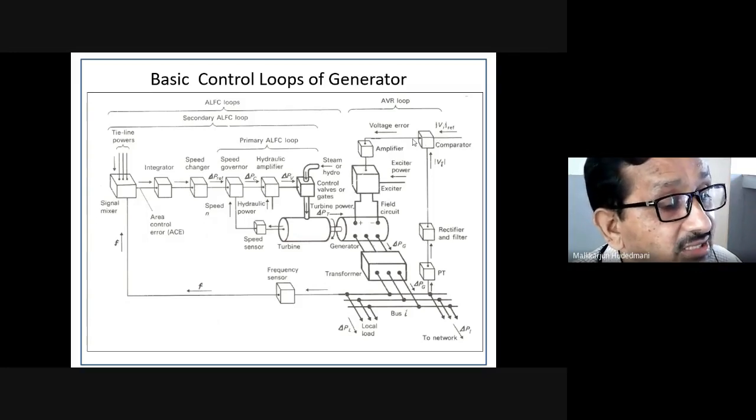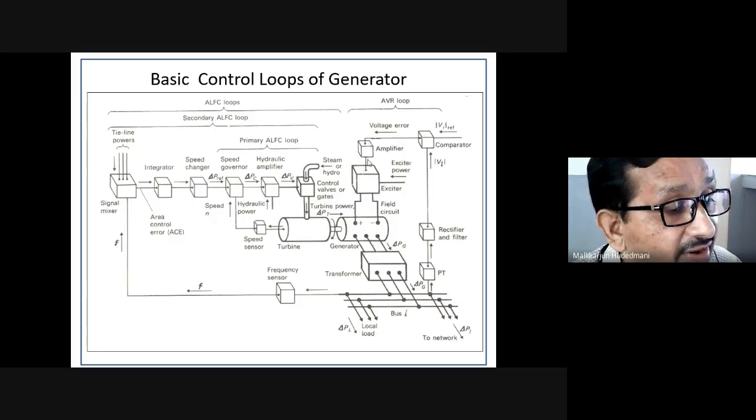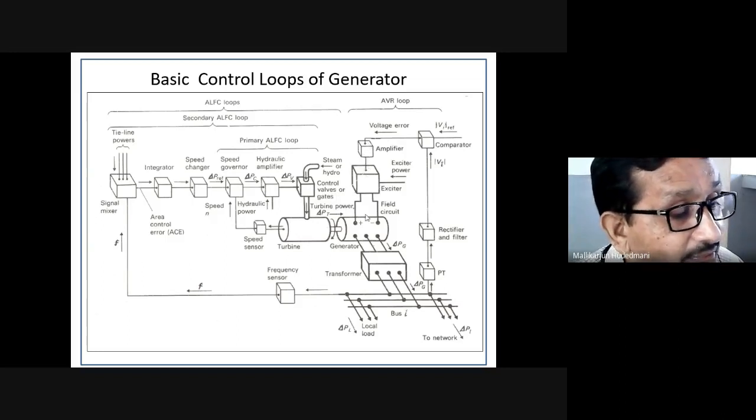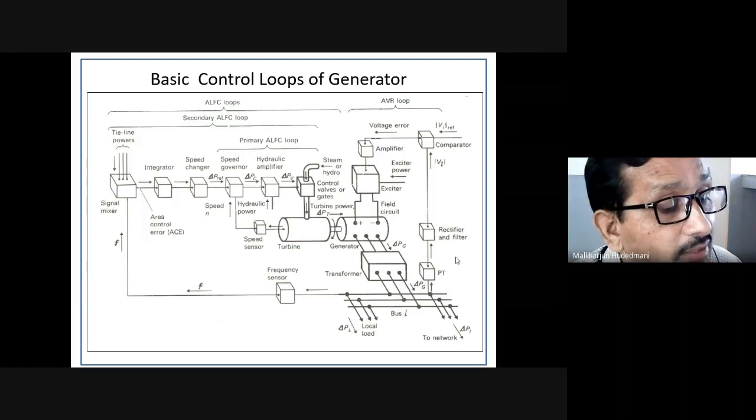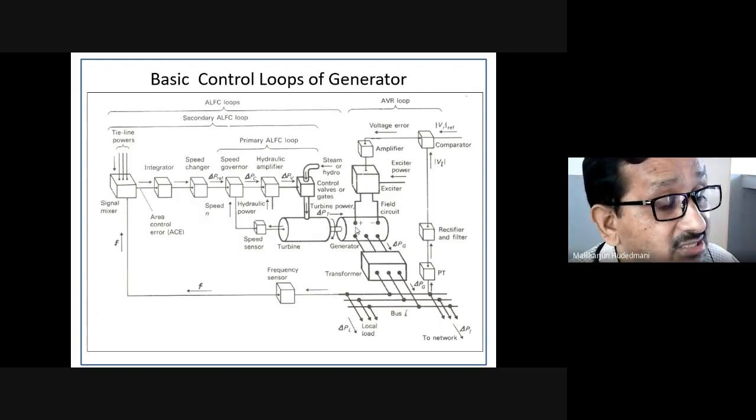And this error signal is amplified and fed to the exciter. If there is an error, that is the stimulus, whether to increase or decrease. If there is no stimulus, what is set is correct. So you can see this loop in this part of the work. This is a closed loop. This is a closed loop working on the generator field system.